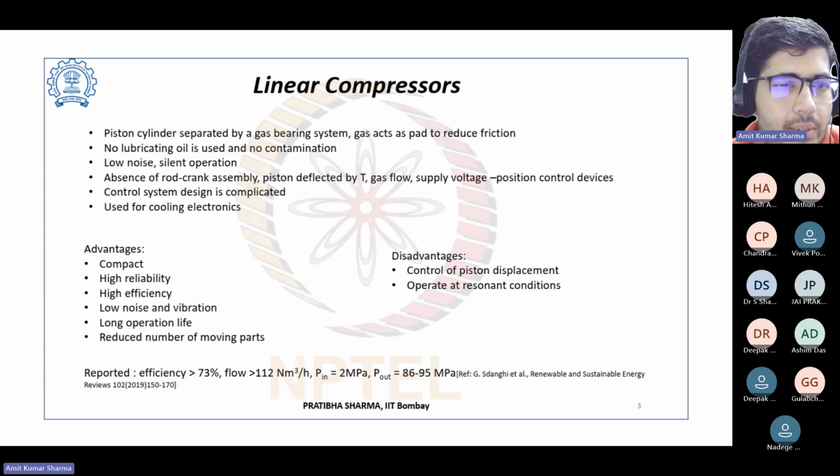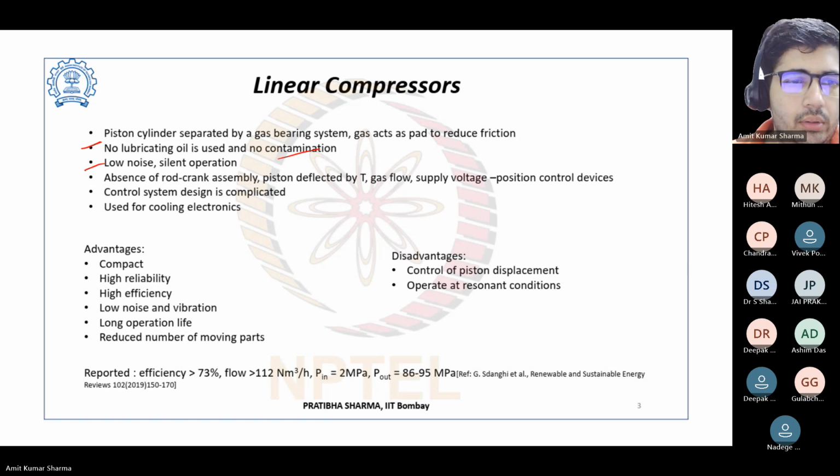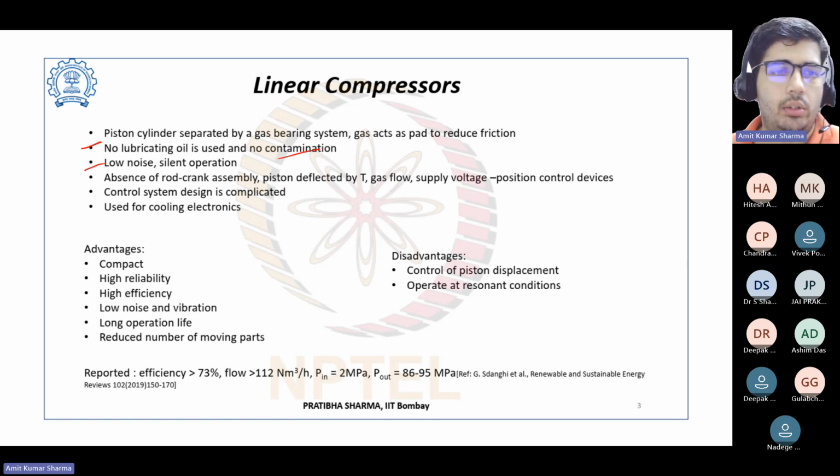The piston and cylinder are separated by a gas bearing system. The gas acts as a pad to reduce friction. No lubricating oil, so no contamination, low noise, silent operation. Okay, we have covered this. Control system design is complicated.